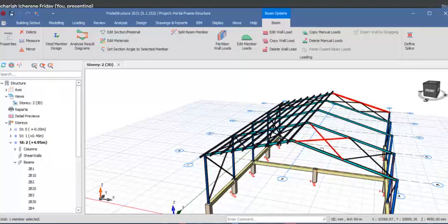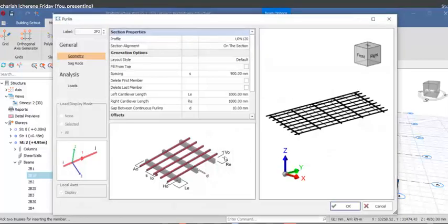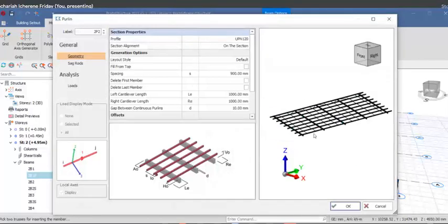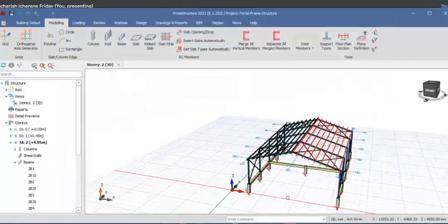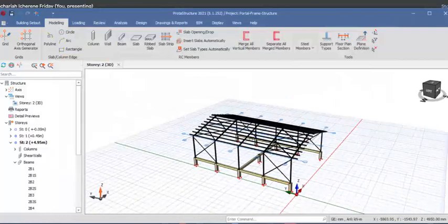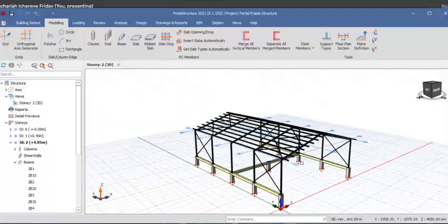So we pick the 2 points. You see, it's not selected. So we need to get back to the modeling tab, navigate to the steel members and activate the polylines again. Pick the first and the last member. We'll use the first setting that we had already. So click on the OK options to have that. Okay. So we have already roofed the ProtaStructure structure successfully.